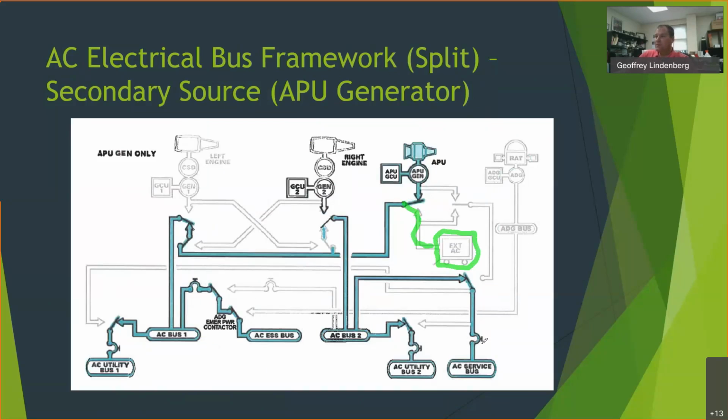You can see there's this possible route here that's called a service route. That's used on the ground if you have a situation where all you want to power is things like lights and maybe a vacuum cleaner outlet or something like that. So those would run off the service bus. It gives some cabin lights, power for a vacuum cleaner, that kind of thing.